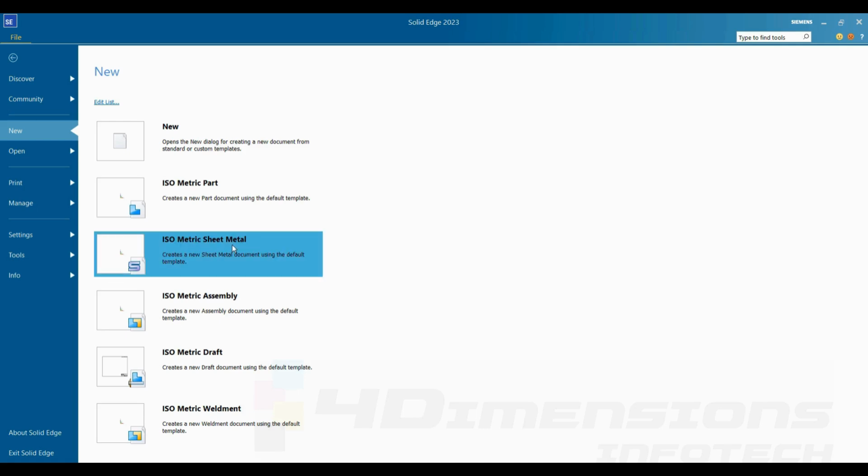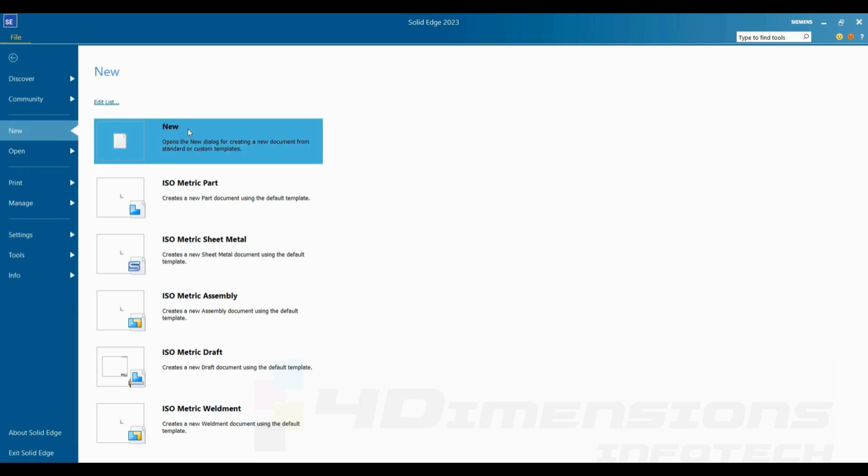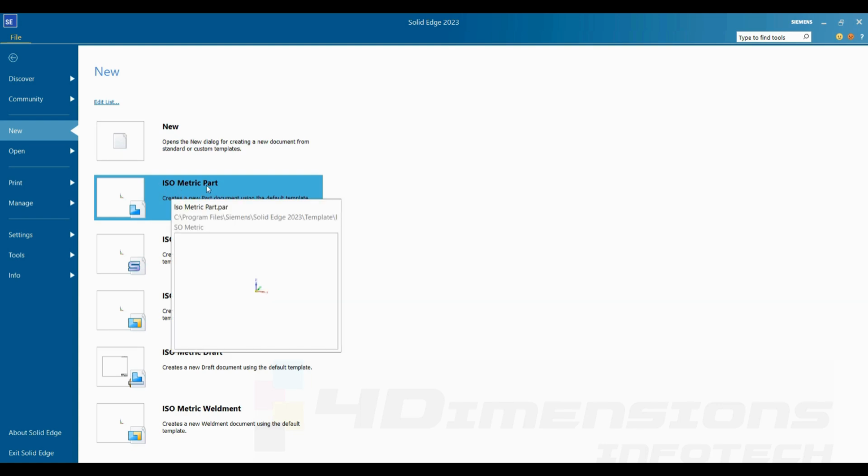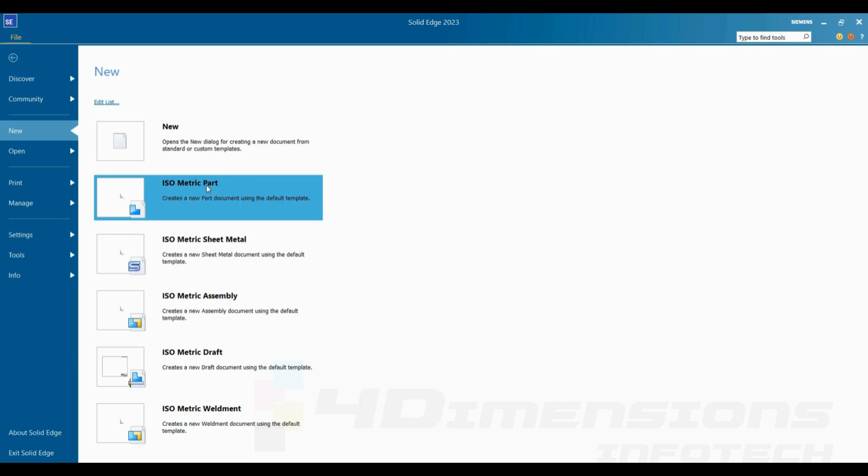So today we are going to start with the Solid Edge second lecture. To start with, I am going to select this New command, and in New I am going to go for Isometric Part. In the earlier lecture we saw the line command, some small settings about starting the sketcher, and then the relations such as vertical, horizontal and connect. That was similar to the coincident relation in SolidWorks. Today we are going to complete the circle command, rectangle and its types, arc and its types, and ellipse.